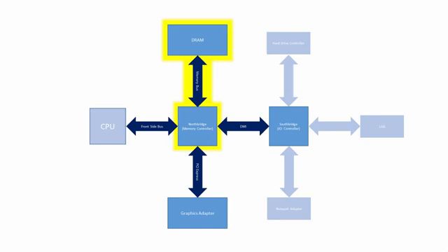The North Bridge was connected to the dynamic random access memory, the DRAM, via the memory bus, and to the graphics adapter via a high-speed graphics bus such as PCI Express, which stands for Peripheral Component Interconnect, or AGP, Accelerated Graphics Port. The North Bridge included the memory and graphics controller circuits, and was therefore often referred to as the Graphics and Memory Controller Hub.